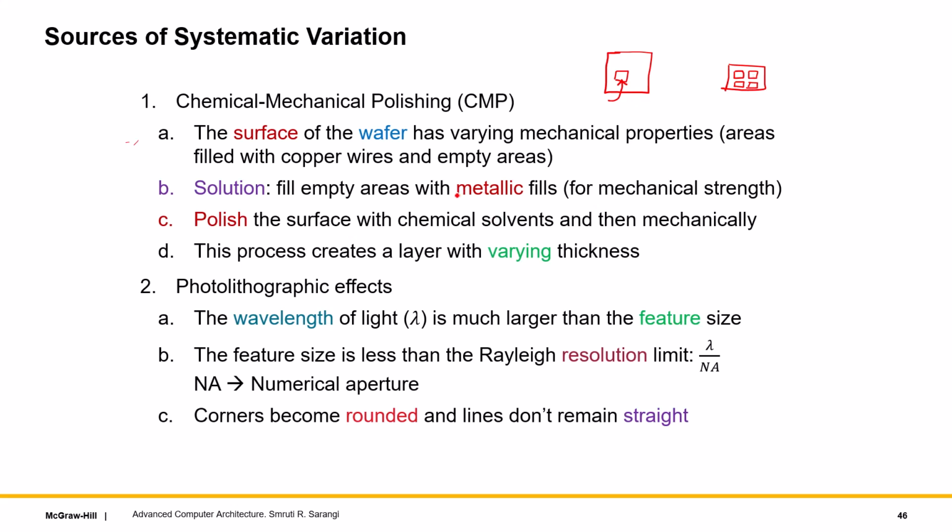What happens whenever we do a metallic fill is that there is a need to smooth it out, such that the entire layer roughly has the same thickness, right? So in this case, fundamentally, we are altering the thickness of the layer for even other things like photoresist and etching and so on. Along with this filling, we are changing the thickness of the layer, so we would like to homogenize it.